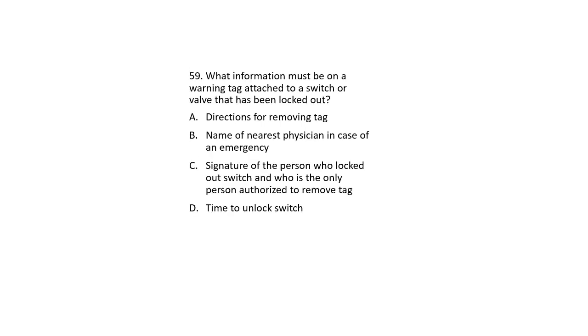What information must be on a warning tag attached to a switch or valve that has been locked out? Directions for removing the tag, name of the nearest physician in case of an emergency, signature of the person who locked out the switch and who is the only person authorized to remove the tag, or time to unlock the switch. The answer to this question is C, signature of the person who locked out the switch and who is the only person authorized to remove the tag.